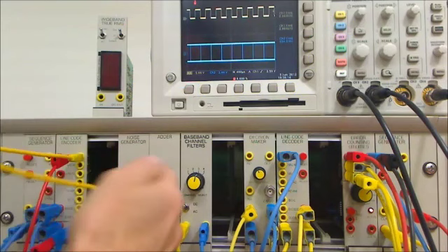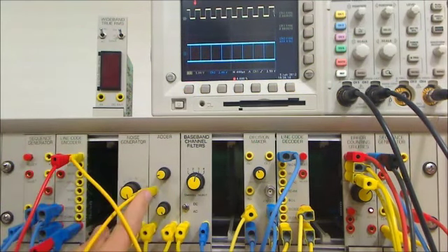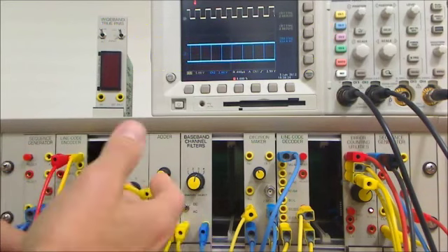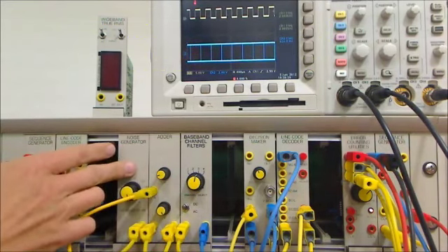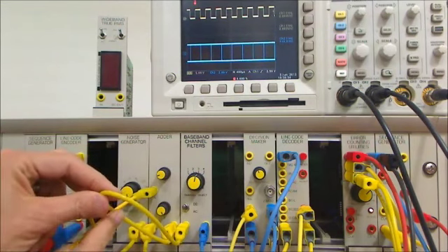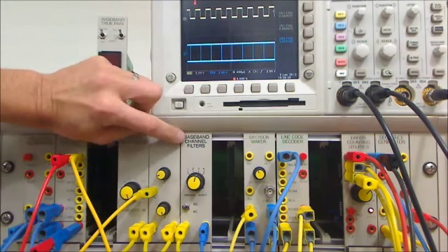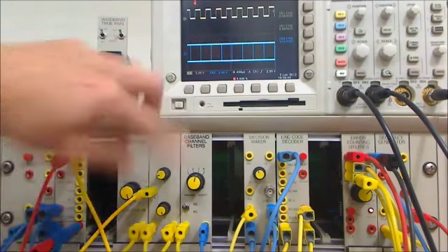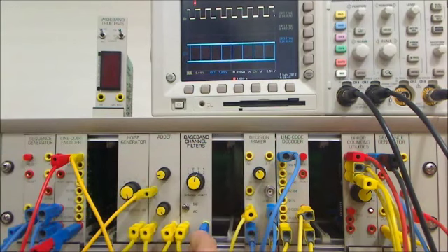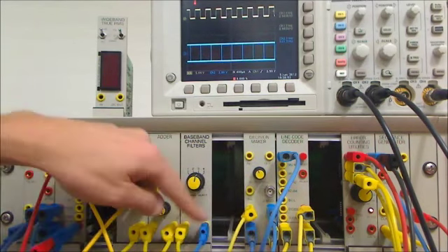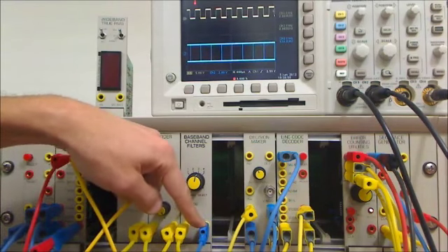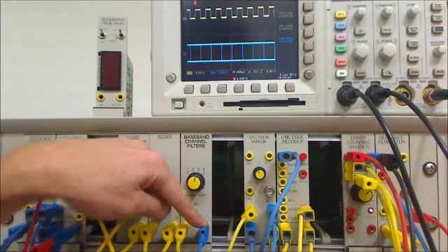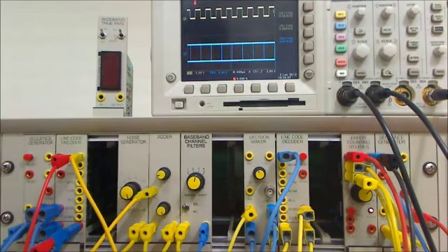We take the line code signal and input it to the adder. The adder makes up the channel. Into this channel we add noise from the noise generator module, and the output of the adder goes to a channel filter, the baseband channel filter, used to restrict the bandwidth of the baseband channel. Then the output of the baseband channel filter at this point is connected to another adder in the macro model in figure 5 to adjust for any DC offsets.